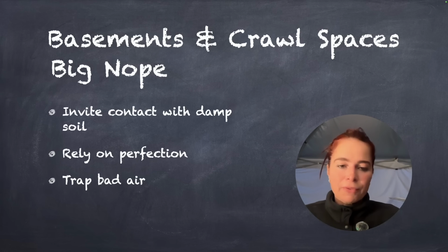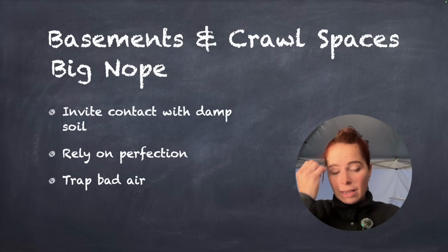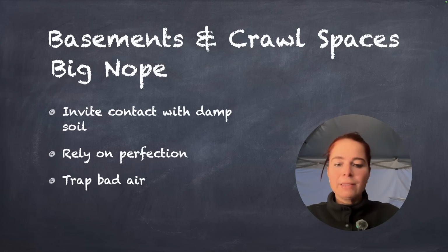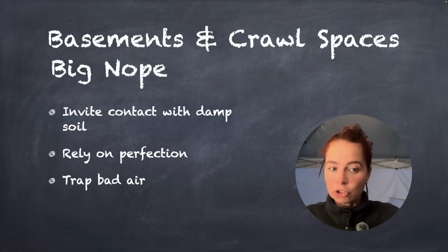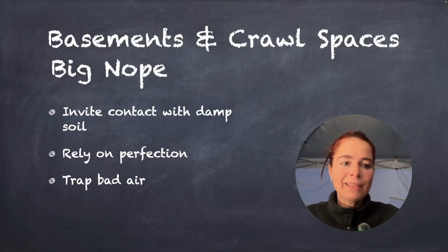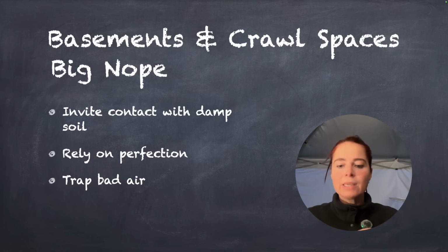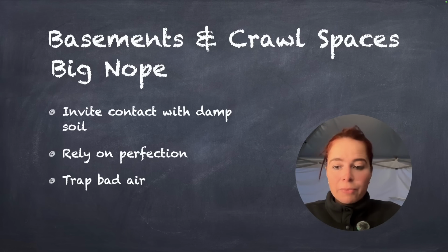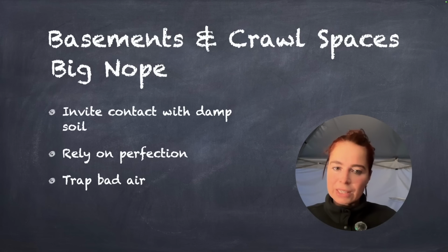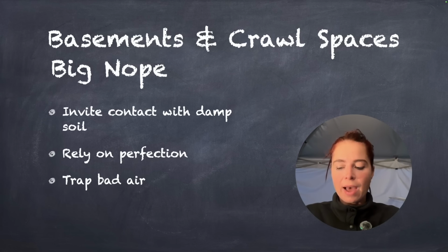Also, they rely on perfection. They rely on capillary breaks, membranes, sump pumps, all of those things can fail, and they normally do, eventually. And finally, they trap bad air. They are reservoirs of mold, musty odors, VOCs, even radon, soil gases. And in an airtight or relatively airtight house, those contaminants get pulled right into the living space, creating a very sick home.